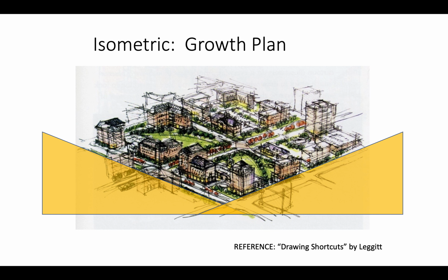Probably two usages of a 30-degree triangle here. In fact, a square corner in an isometric view is going to be a foreshortened or distorted segment, as you can see. If this is a true square in isometric view, you are in fact looking at a diamond shape, and it does have a type of foreshortening or distortion.